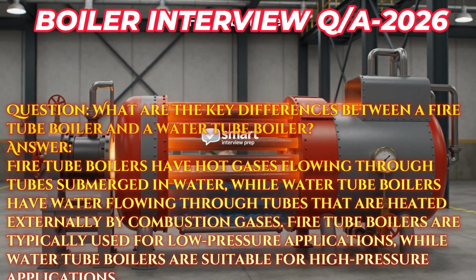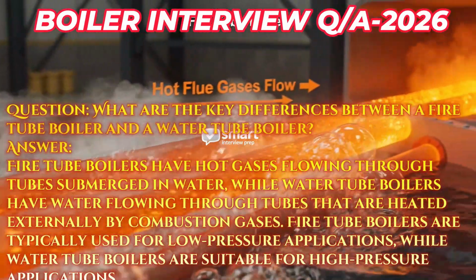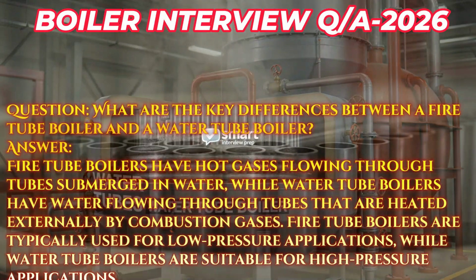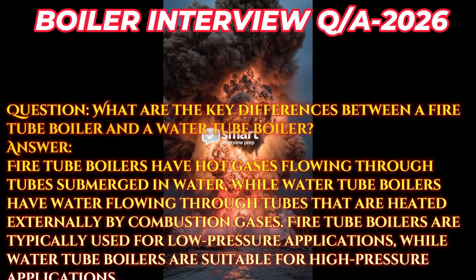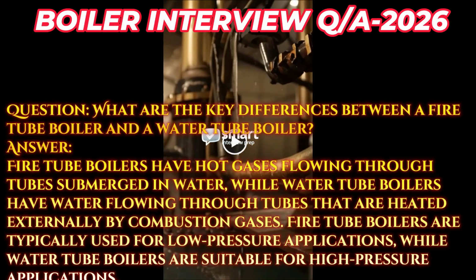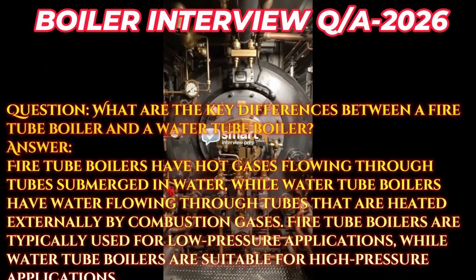Question. What are the key differences between a fire tube boiler and a water tube boiler? Answer. Fire tube boilers have hot gases flowing through tubes submerged in water, while water tube boilers have water flowing through tubes that are heated externally by combustion gases. Fire tube boilers are typically used for low-pressure applications, while water tube boilers are suitable for high-pressure applications.